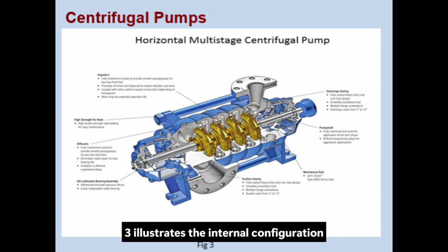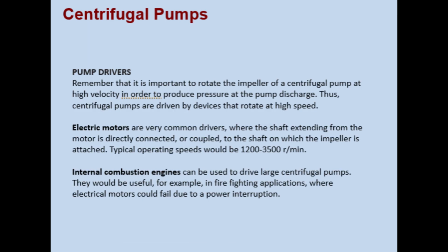Figure 3 illustrates the internal configuration of a multistage centrifugal pump. You can see the series arrangement of impellers, each contributing an incremental increase in pressure. This stacking approach allows centrifugal pumps to achieve pressures well beyond what a single-stage design can deliver, while retaining the benefits of centrifugal pump technology, such as high flow capacity. Let us now discuss pump drivers.